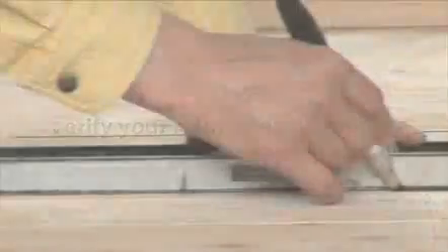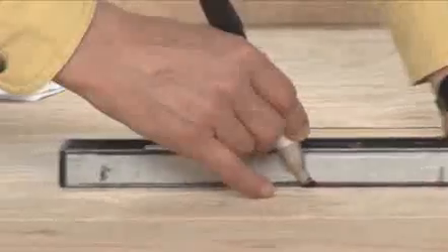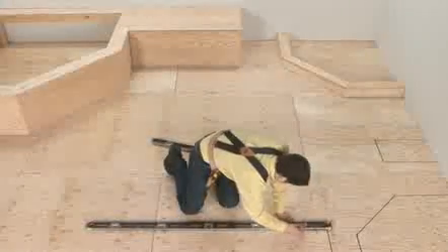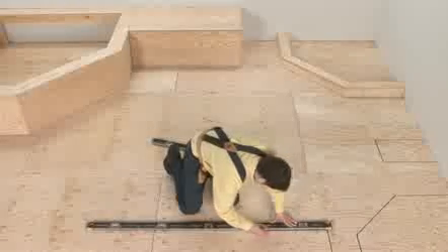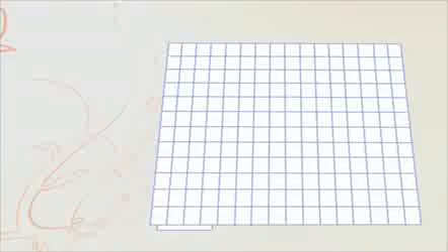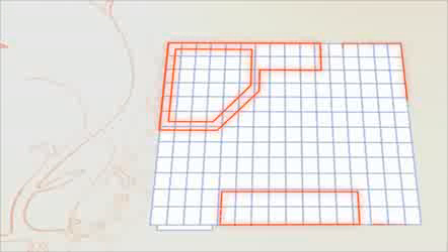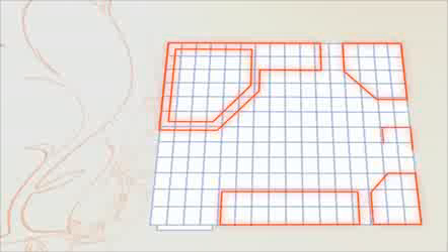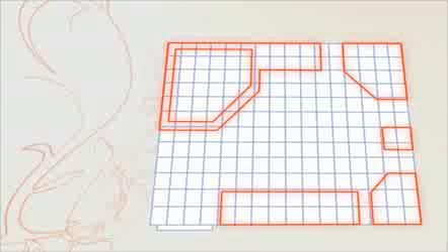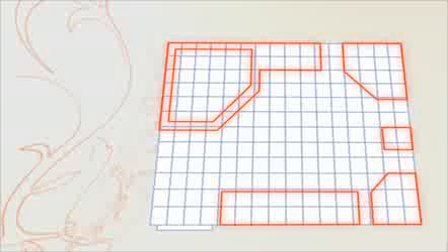Let's start by evaluating the surface to be heated. On the floor, mark the outline of any obstacles to be skirted, such as fixed furniture or furniture under which air cannot circulate freely. In our example, we need to deal with a bathtub, a sink enclosure, a shower, a corner cabinet, and a toilet. If your space is irregular, our example will illustrate what you need to do.